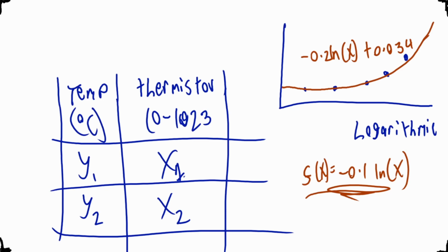it is. One of the things you'll need to do your lab report on is to what degree you're confident in this reading versus the reading that the LM35 gave. And so within this, it's up to you then to read the datasheet of the LM35. Literally Google Texas Instruments LM35 datasheet. You'll find it online. Same with every other component ever in existence. You can find the datasheets online if you Google for them. And you can look at the accuracies of that, and maybe the accuracies of the thermistor or the accuracies of the Arduino. And you can comment about how accurate you think your thermistor's calibration is compared to the actual real world temperature.